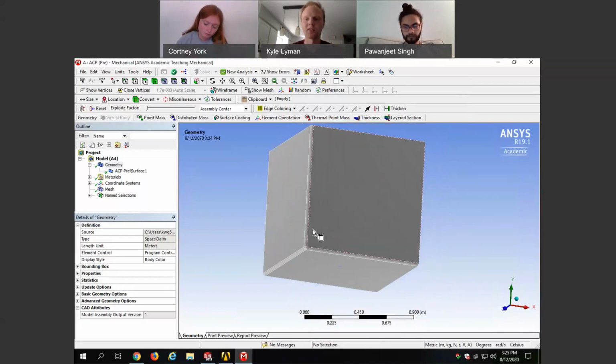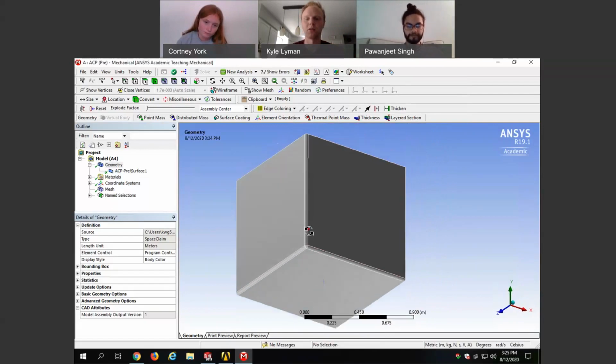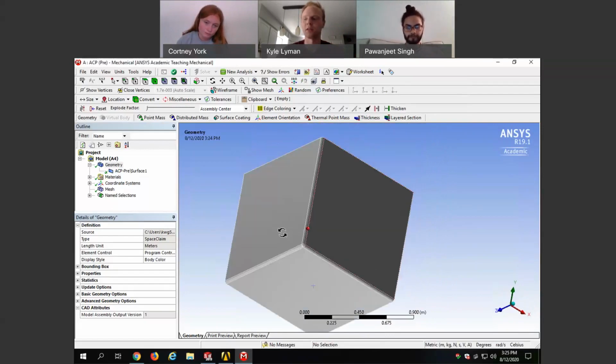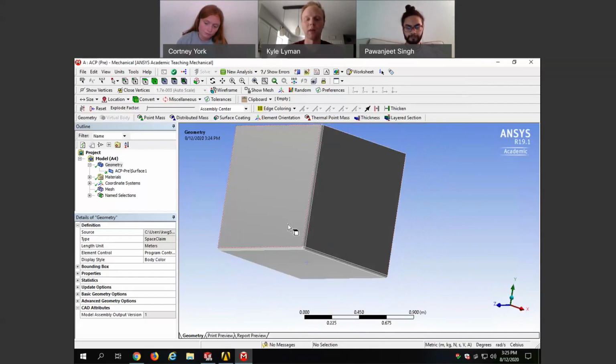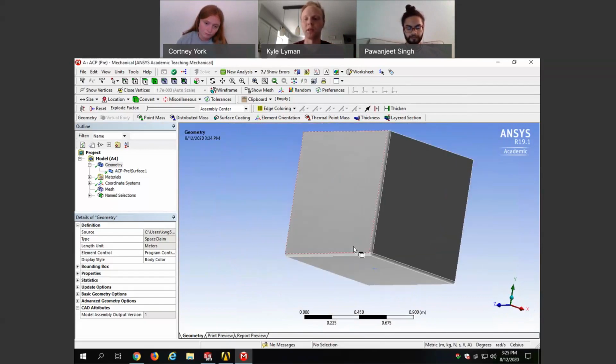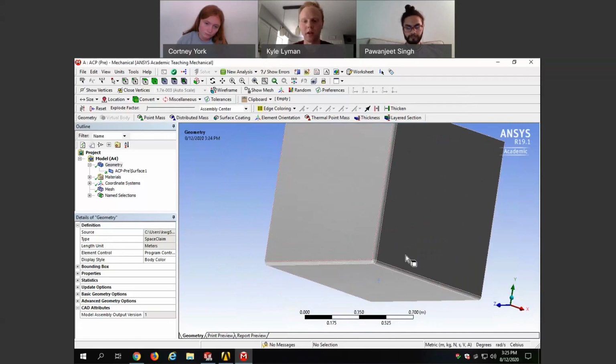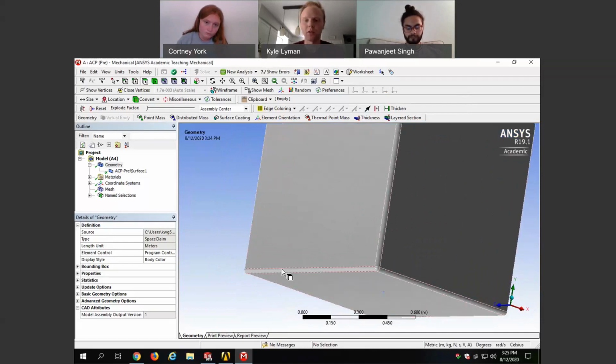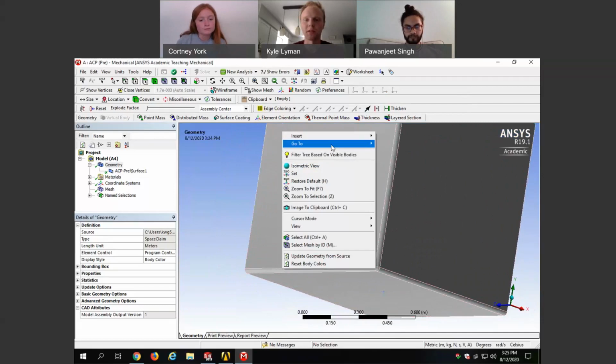Also, the difference between panning and zooming. So for rotating, just click on the center of your scroll wheel, and then if you want to pan, hold control and click the center of your scroll wheel, and you can pan. But side note, I'm going to name these faces.